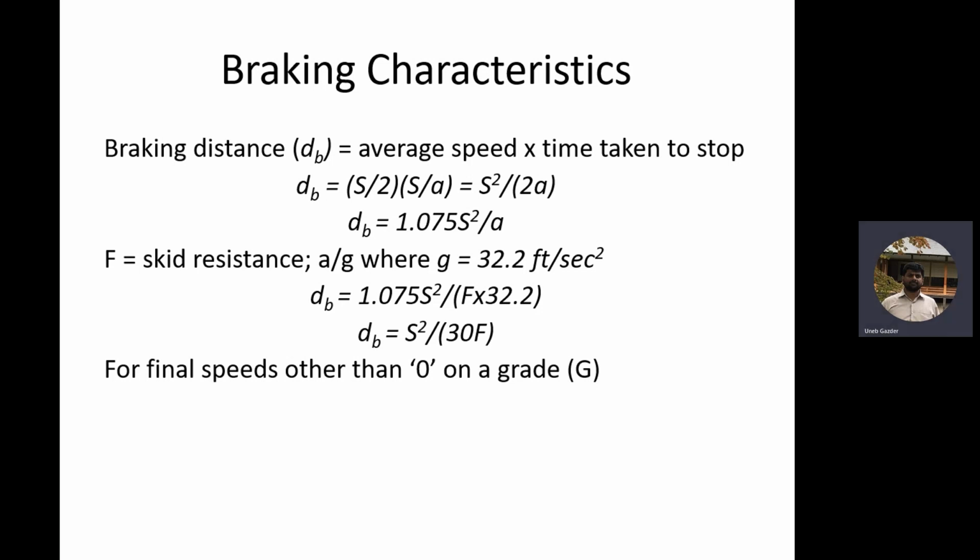If your car is moving north-south, side friction is east-west, across. The skid resistance is along the path, so it is north-south. So their values are different, their meaning is different, their direction is different. You cannot put the value of one for the other, and they are used in different equations.